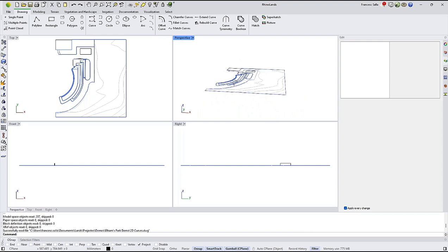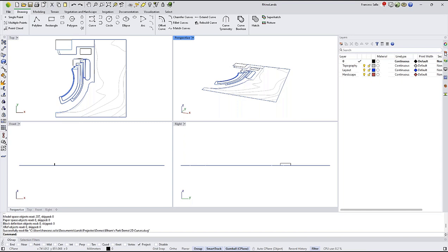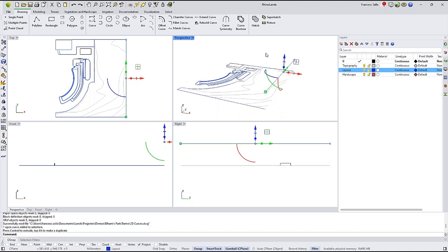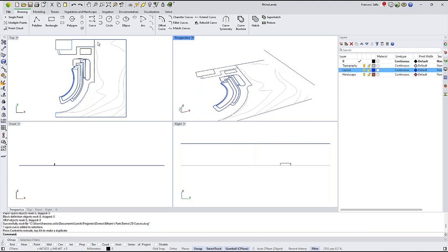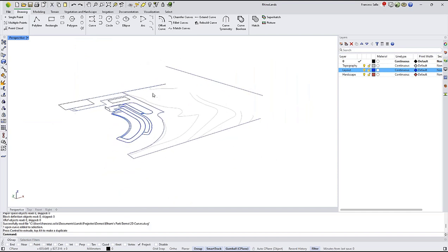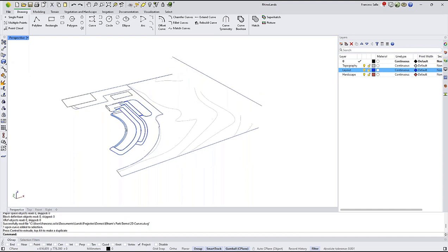Here you can see all the 2D drawings that come in this DWG file. If we explore the layers, we can see that some objects are stored in these different layers. If we select these objects, we'll see control points, and we have this gumball to move the elements. So it's very easy to edit these objects and navigate through the viewports. Just double click to expand a viewport and work from a single viewport. On the left side, we can find transform commands such as copy, move, rotate, or scale, and other commands to work with the object that we select.